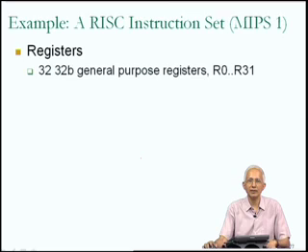So in brief then, the important general purpose registers of the MIPS1 are the 32 general purpose registers R0 through R31, of which R0 is hardwired to 0 and cannot be modified. R31 is implicitly used by some instructions. In addition, there are the high and low registers, which are implicitly used by the multiply and divide instructions.